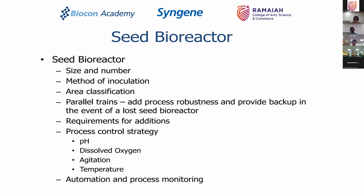Now, seed bioreactor, the factors to be considered are the size and the number, depending on 1 is to 10 scalability, 1 is to 5 scalability, depends on the size. So you need to decide what is the size of the seed bioreactor, what are the number of bioreactors, how many bioreactors will I run to support one production. Sometimes you may inoculate two different seed bioreactors into one production bioreactor, or sometimes you run them parallel so that if one fails, the other one is available, and then you throw the other one down the drain just because you can't inoculate it into the production fermenter.